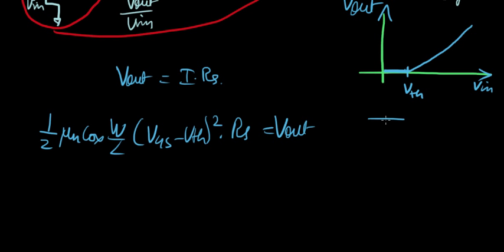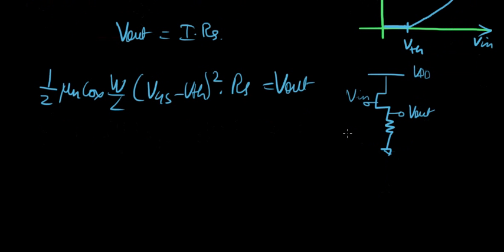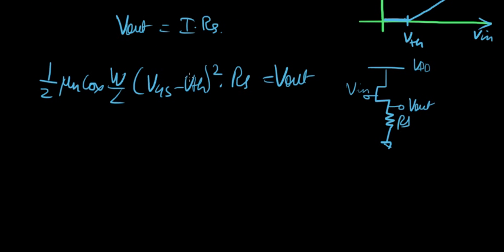Let me draw the circuit here again. So as we did with common source, I'll be drawing the circuit a lot of times so that it just gets imprinted in our minds, right? Helps me too. All right. Let's see here. VGS here is pretty simple, right? VG, the input voltage, minus VS, the output voltage, right?